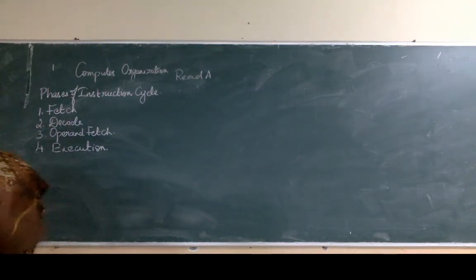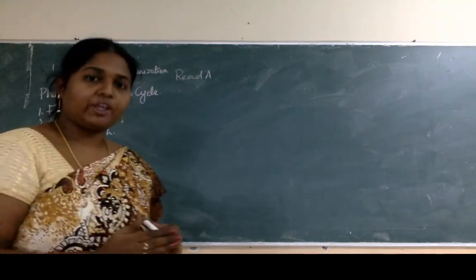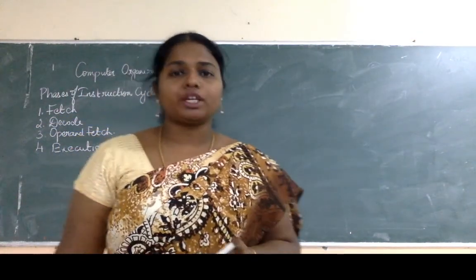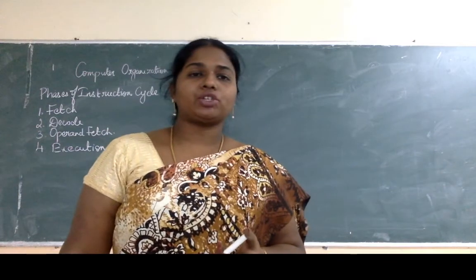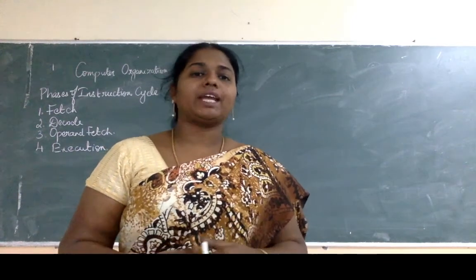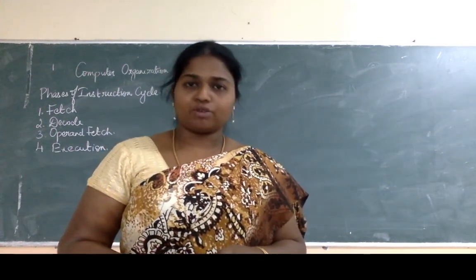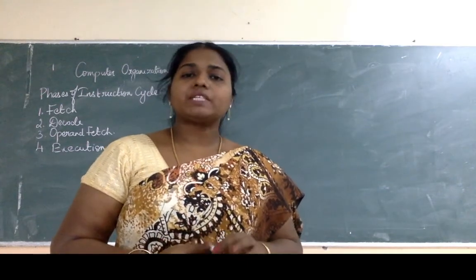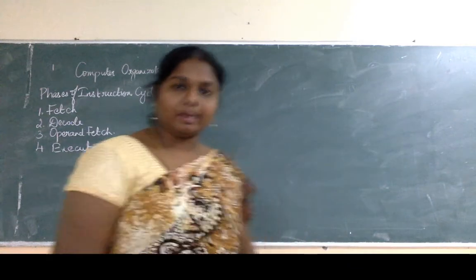The first one is the instruction fetch, followed by decoding of the instruction, and then you move on into the operand fetch, or fetching of the data that is required for execution of that instruction. Then you perform the execution of the instruction. And we have seen a primitive circuit that can help us do that.